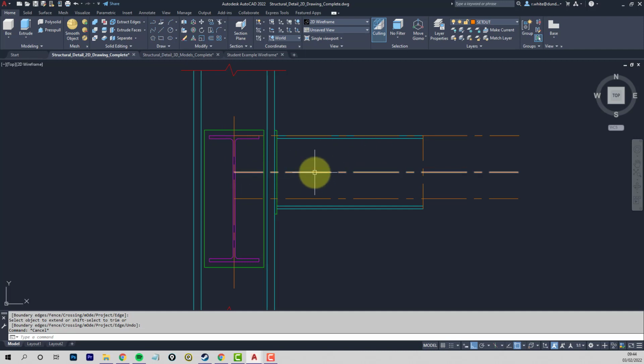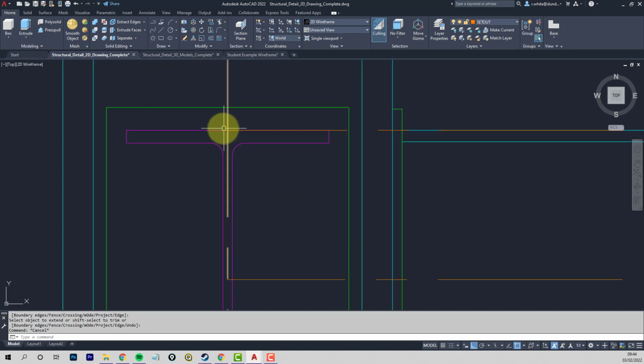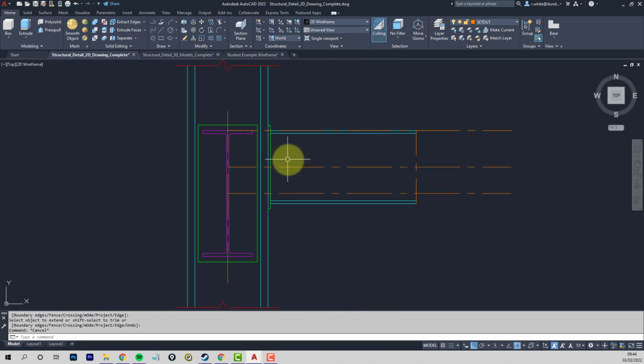Okay, so we'll do the small beam first. So we're going to pick it up by this point, because we do know the height of the column. So we'll pick it up, and then we'll change coordinate system, and then put it into position. The command for that is Shift Control C. So it's Shift and Control at the same time, and then tap C. So you get a command called Copy Base. The base point is the middle of that top flange. It's the end of our setting outline there, but we pick up this line.